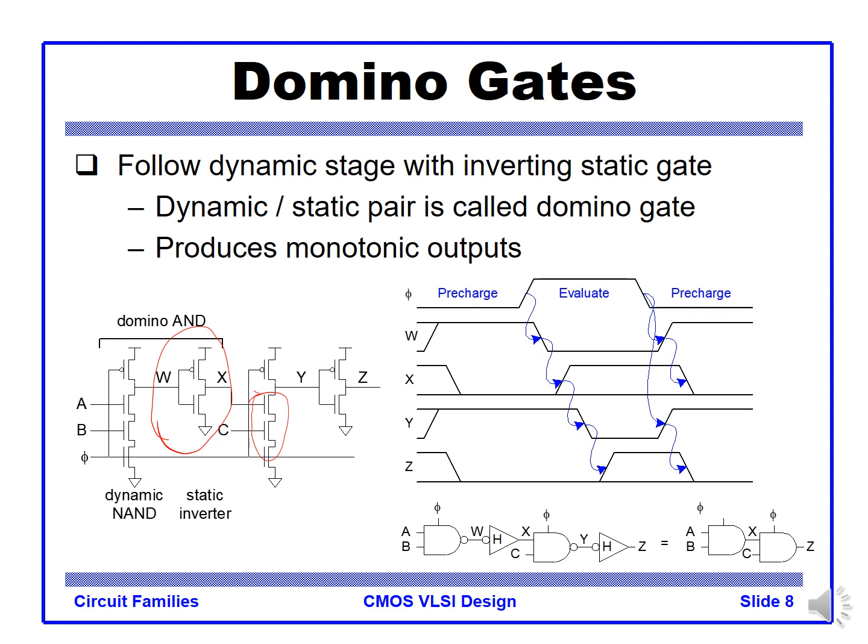So the input that momentarily stayed high was disabled. This is the timing diagram. We have pre-charge and evaluation periods. When we pre-charge, the internal nodes W and Y pre-charge to high, and also the inputs to all the domino logic are always disabled, going to 0. So the pull down is disabled.